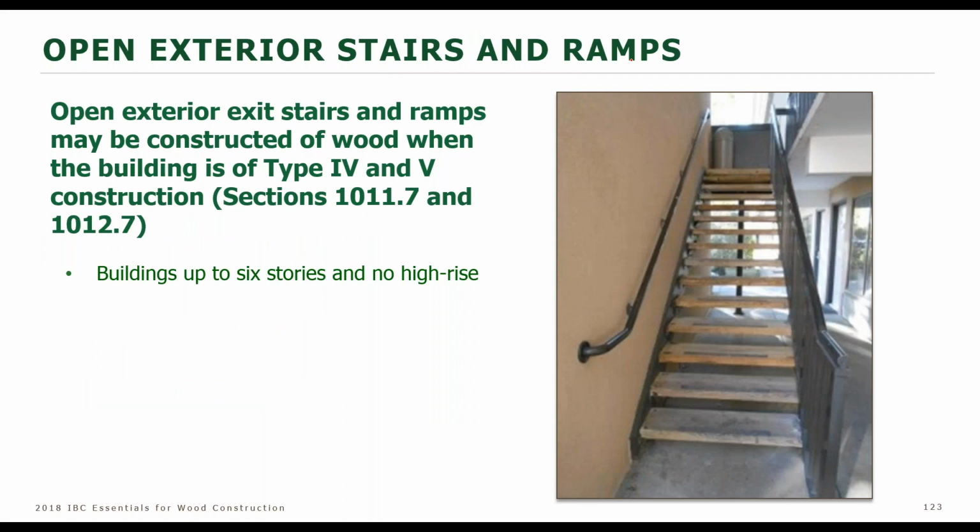You can have wood stairs on the exterior of a building. This is a common question. If the building is limited in height up to 6 stories, if the building is type 4 or 5 construction, you can have exterior stairs of wood. So check the conditions in these sections.